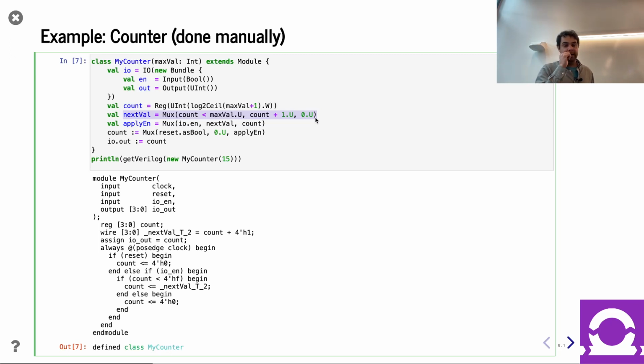In today's lecture, we're going to see multiple flavors of counter written manually by us. If you go digging in the Chisel standard library, you'll find that counters are included. After this week, you should use the library counters, and we'll come back to that in a few lectures. If you look under the hood of those counters, they're optimized. They actually have that check: is this a power of 2 or not? Because of that, they can make the hardware a little bit more efficient in those cases.